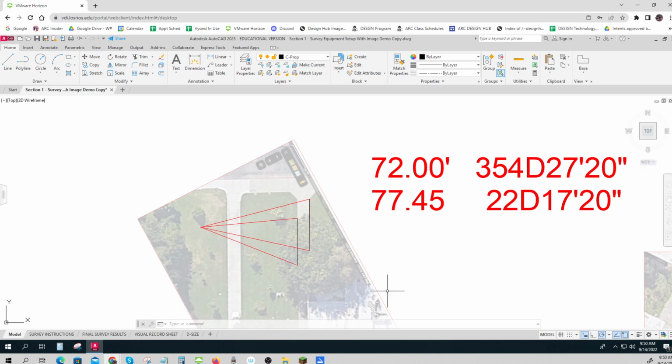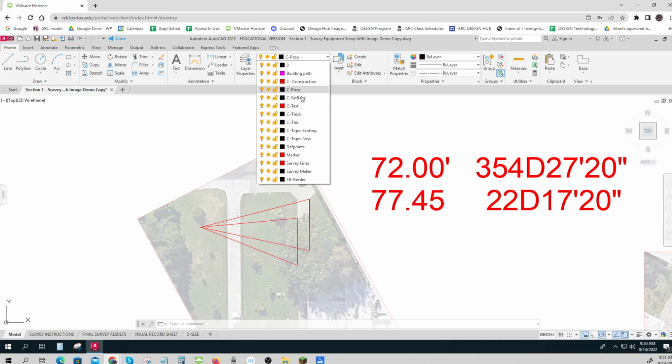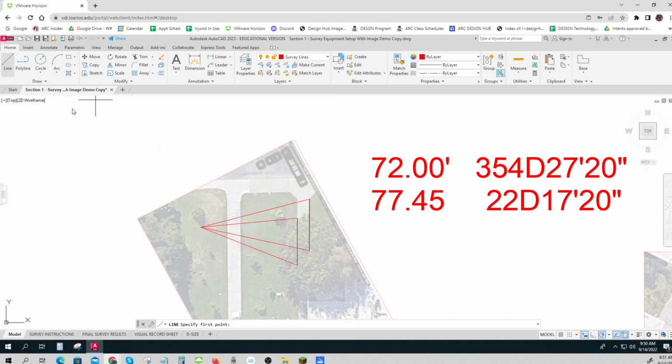The main thing is when you're using dynamic input, that when you draw a line, there it is, get your starting point, get the angle 0 correct, and type your distance, 72.00, hit tab, and then move your cursor so that you know you're going positive clockwise. Then you can type it in. There you go. I hope that helps out.